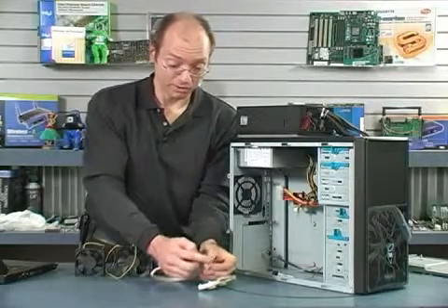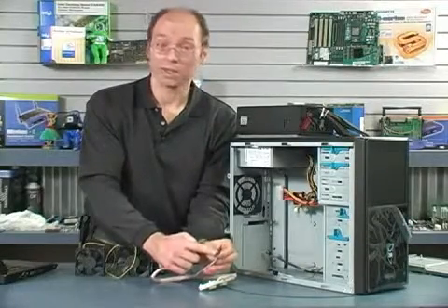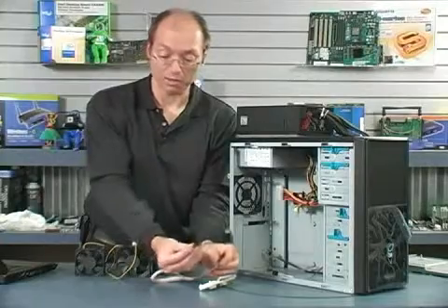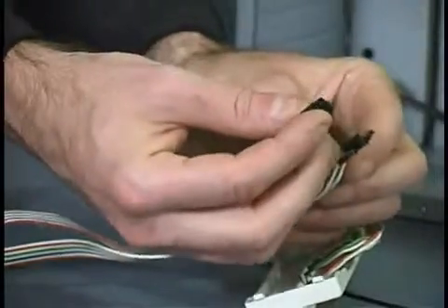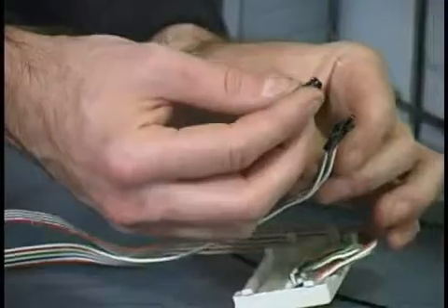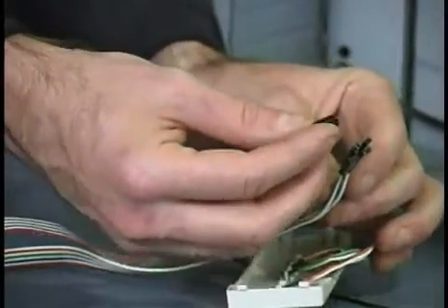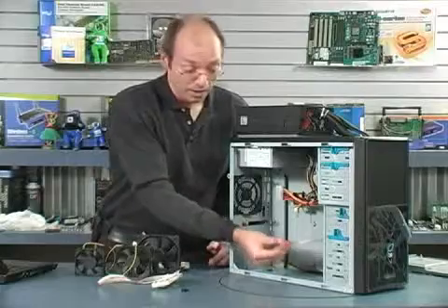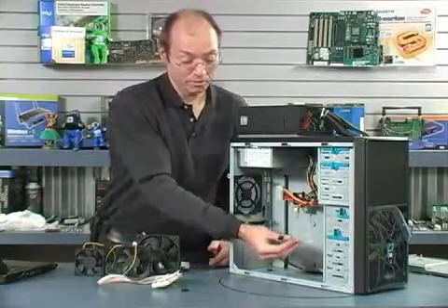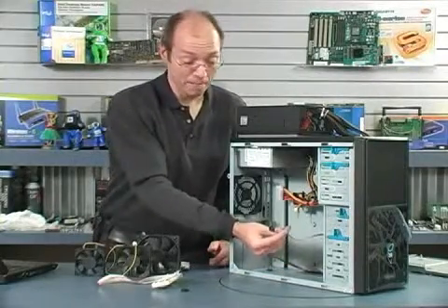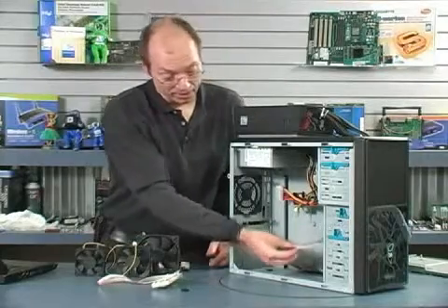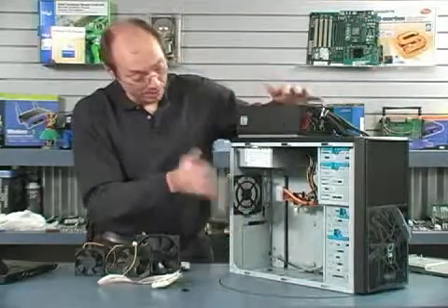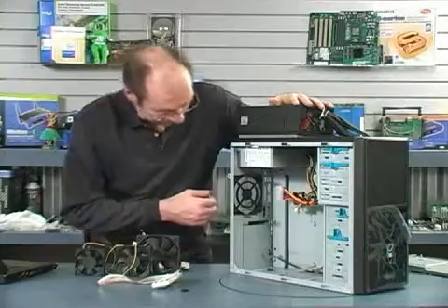And I simply insert the pins. I don't even have to cut the wires or do anything with the terminals. These are the same terminals that go into this connector, and I simply insert them in this connector in the right sequence and right order, and you find the documentation for that in my book. And then, after just a few minutes of work with this, from that point on, I now have a single front panel connector on my case. So anytime I remove the motherboard or have to plug it back in, it's one single keyed connector, very easy, nothing to mess up. That is a tremendous tip.